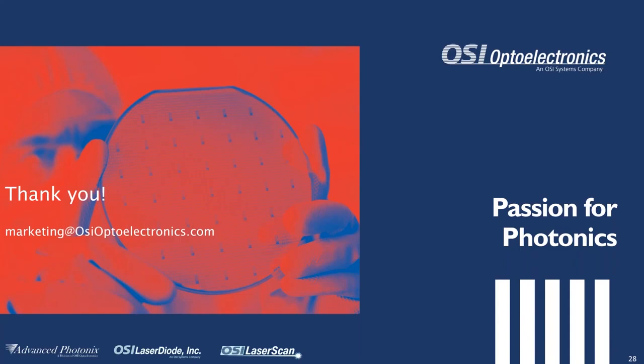Assuming that we need about 1 millimeter thickness of silicon, well, it's possible, of course, but then you have to apply really good beveling, for example, of edges to sustain the high reverse bias that supports avalanche in this kind of application. Frankly, I myself did not build this kind of APDs working for X-rays. I built many other types of APDs, but not anything like that.